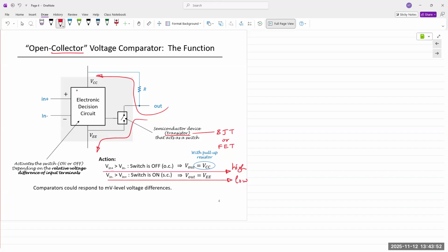In all textbooks and most images we encounter, it is omitted, so it's simply a triangle like an op amp, and it's left to the reader to understand that this is a comparator. But these are two very different devices. Op amps can be used as comparators, but comparators cannot be used as op amps. So I like to explain that comparators are a subset of op amps. That's not how everyone describes it, but I like it because op amps can be used as comparators, but comparators cannot be used as op amps.